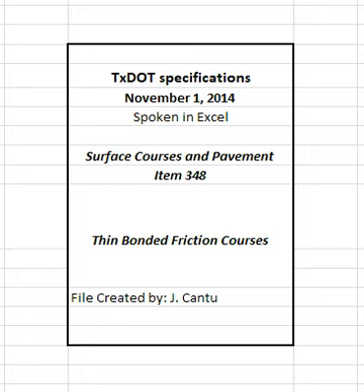4.9 Acceptance Plan. Sample and test the hot mix on a lot and sublot basis. A production lot consists of 4 equal sublots. Lot 1 will be 2,000 tons. The engineer will select subsequent lot sizes based on the anticipated daily production. The lot size will be between 2,000 and 4,000 tons. The engineer may change the lot size before the contractor begins any lot.